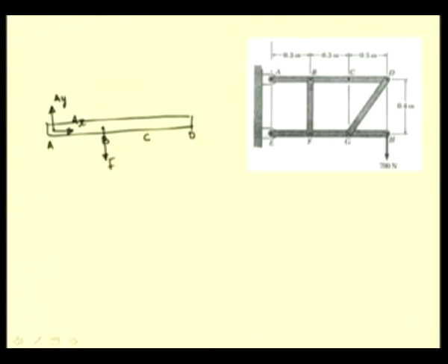So, we have this force FBF of known direction and unknown magnitude. At D, again we have a two force member. So, the direction of this force is known, but the magnitude is unknown. So, this completes the free body diagram of this member A, B, C, D. Obviously, one has to mark the various dimensions in order to solve any moment equation.